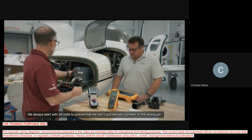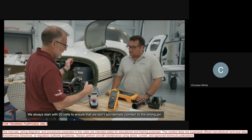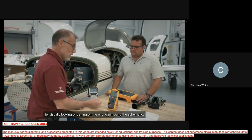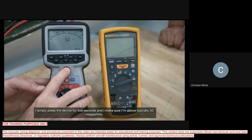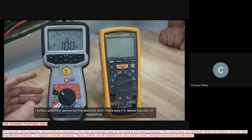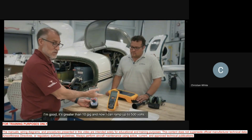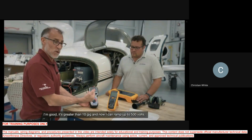We always start with 50 volts to ensure that we don't accidentally connect to the wrong pin by visually looking or getting on the wrong pin using the schematic. I simply press the device for 5 seconds, and I make sure that I'm above typically 50 megaohms. I'm good. It's greater than 10 gig. Now I can ramp up to 500 volts.